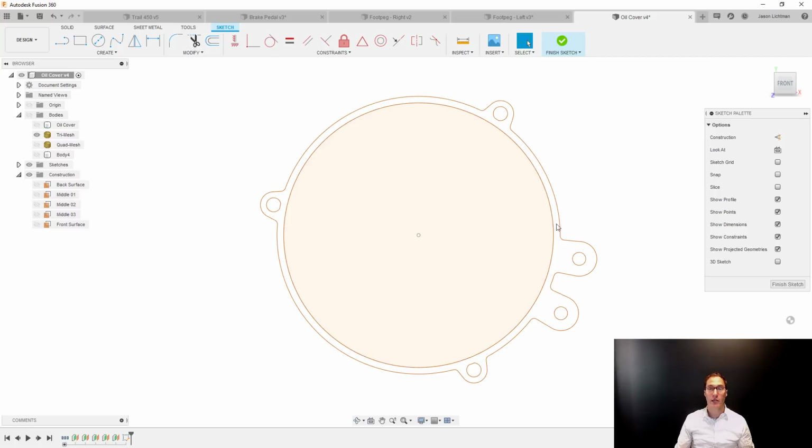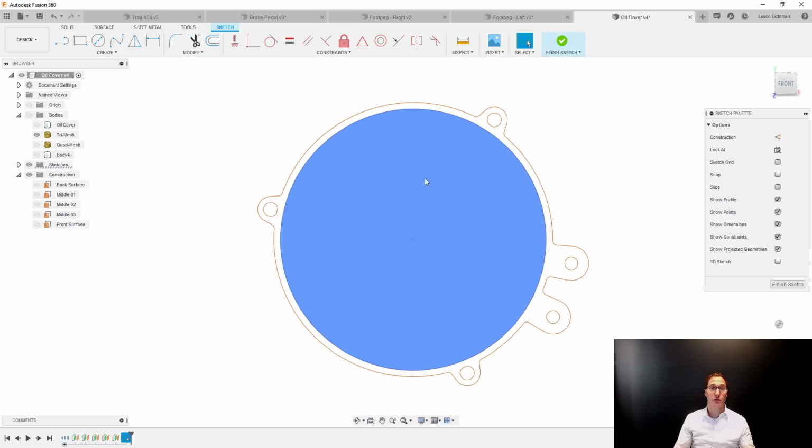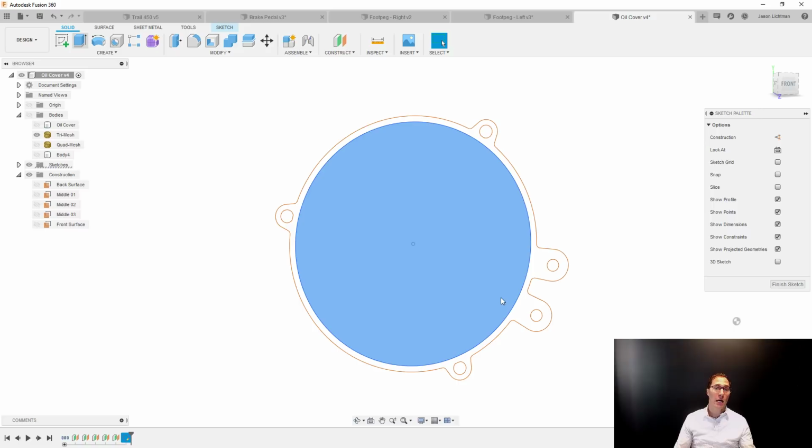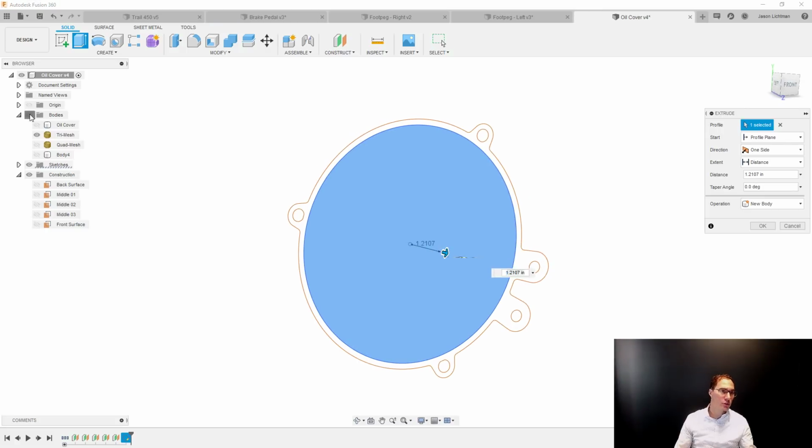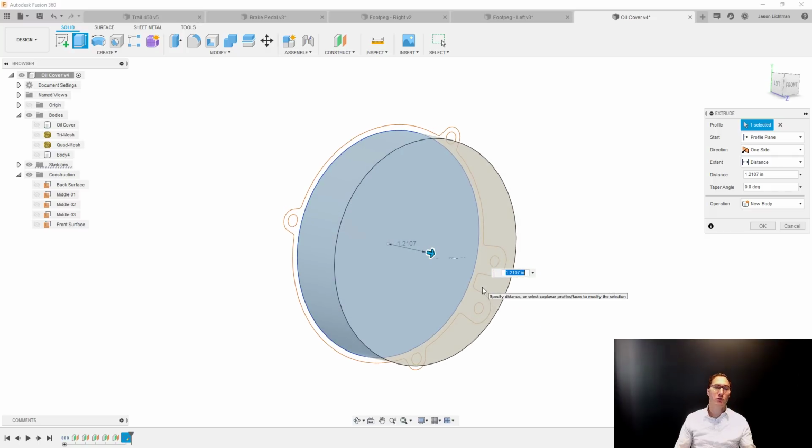Now I'm going to hit OK, and you can see that this is highlighting in bold the outer contour, the profile as we call it in Fusion. I also get the peach fill on the inside, and those tell me that this is a proper sketch. If I wanted to just take this and extrude it, I could do that using proper solid modeling techniques. I could also do a surface extrude or anything else that I want to do, without any problem. But maybe I want to do something else. And this is, by the way, oh, I have to show my solid. I had the triangular mesh. This would be a solid cylinder based on that. Let's cancel it.